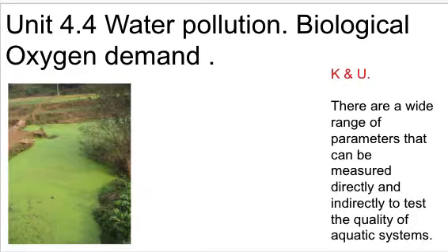That's very important because you don't want photosynthesis to occur. So you put it in a dark place at 20 degrees centigrade and you leave it for 5 days. After those 5 days are up, you carefully measure the oxygen concentration, and the difference between the oxygen concentrations before and after gives you your biological oxygen demand. We're going to undoubtedly do that in practical terms in the lab.